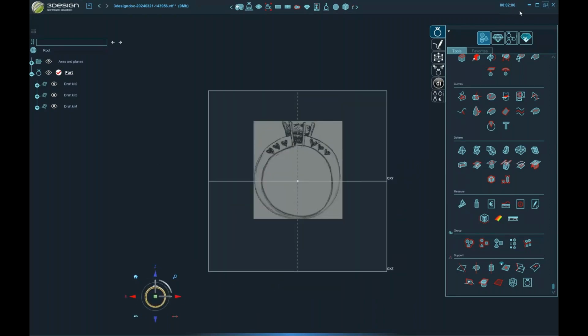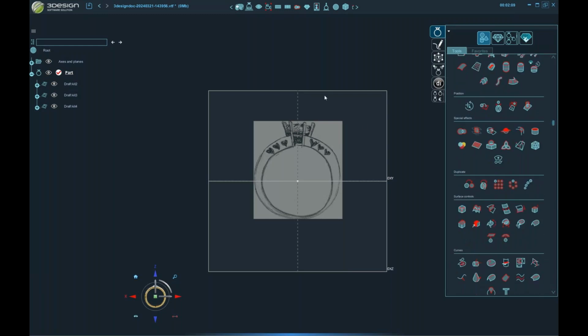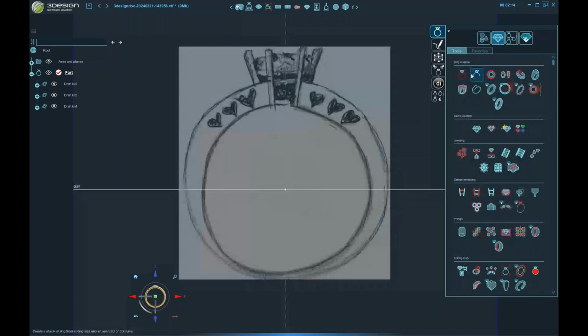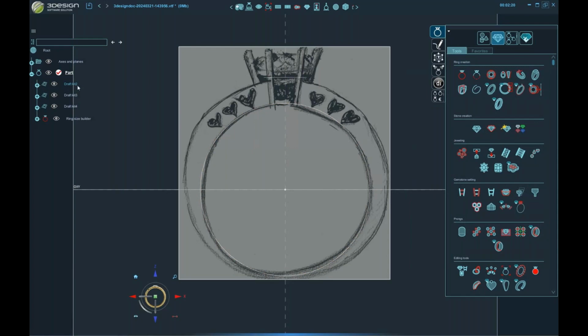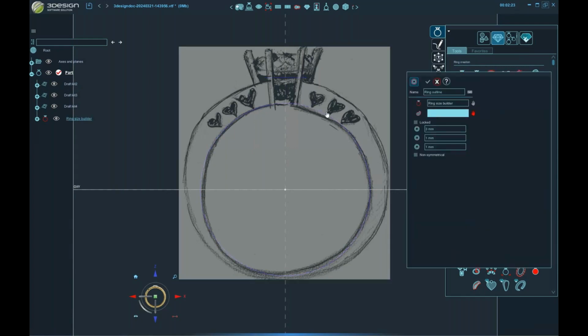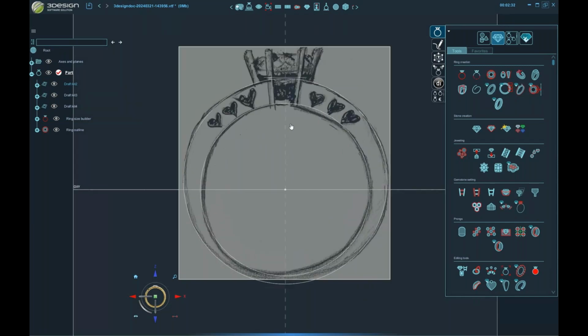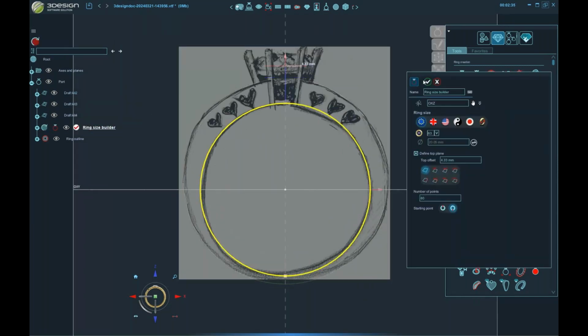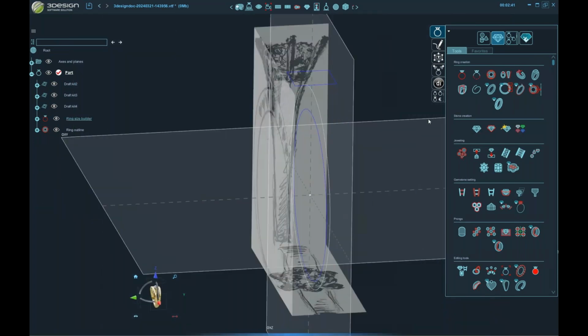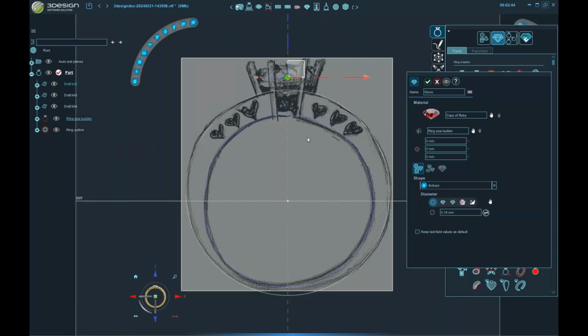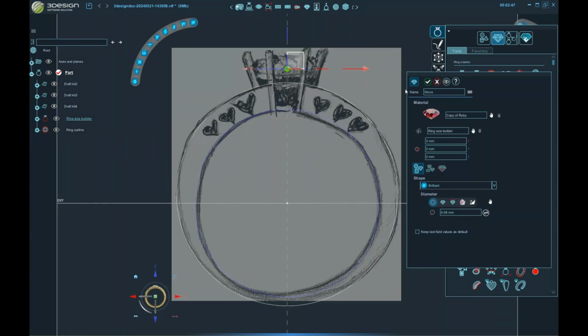Look at that. We have 2 minutes on the timer, and I will do the creation with you. First I have to set my ring size. 54, oh no, this is a 63. So leave it on 63. Okay, now I have to draw the external shape. So I follow my draw like that, my sketch like that. I will set the position of my stone. So I set a little plane which is above my ring size. I just have to select the ring size and set the stone now like that.